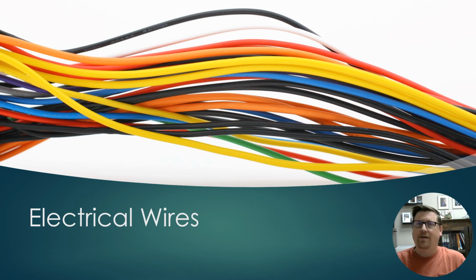I say derate. All of these factors is what used to be called derating in the code book. Now it's been broken down into separate parts for each thing that you do. So like we're going to talk about correction factors for temperature. We're going to talk about adjustment factors for the number of wires that we put into the conduit. And so those are going to be all factors that go into us choosing what wire size we're going to use for a specific situation.